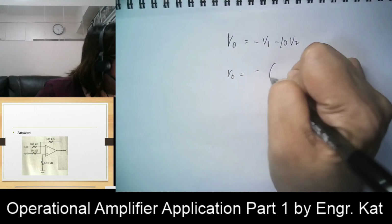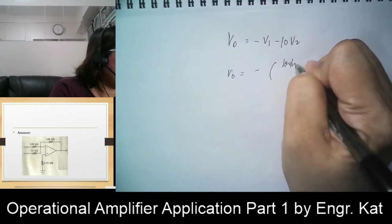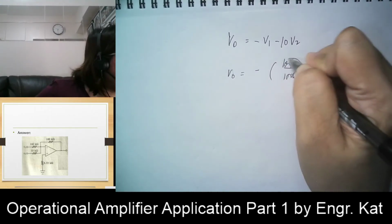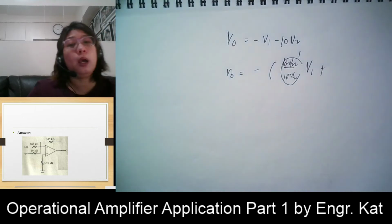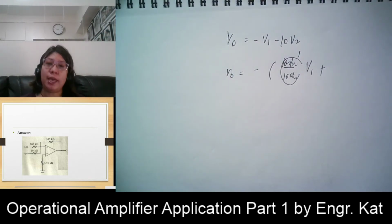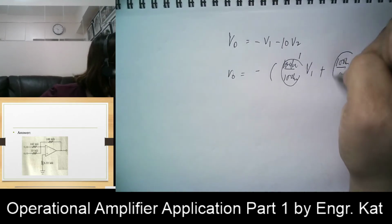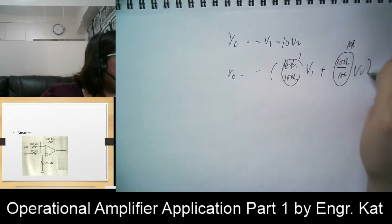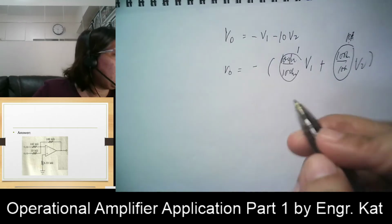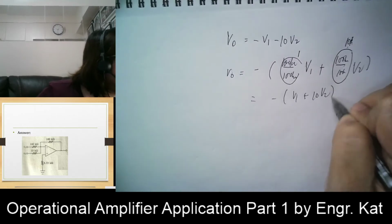So this is negative, okay? So we have here 100 kilo ohms divided by 100 kilo ohms. This will give you a gain which is equivalent to 1 times V1. And then you have to choose a value that when you divide it into 100, the answer will become 10. That is 100 kilo ohms here divided by 10K. So this ratio here will give us a value which is equivalent to 10 multiplied by our V2. So in this case, that will give you minus V1 minus 10 V2.